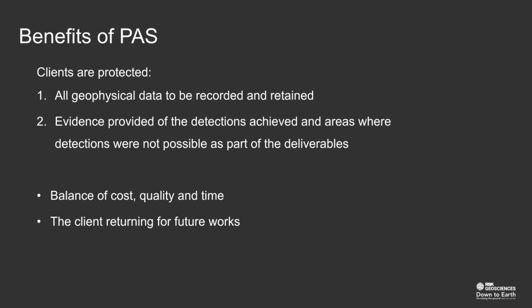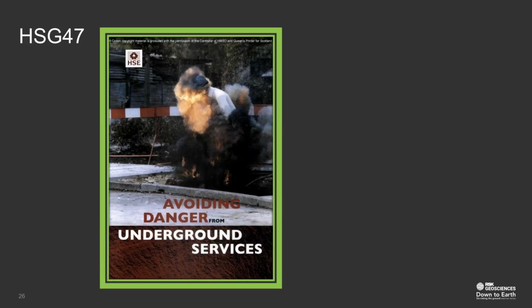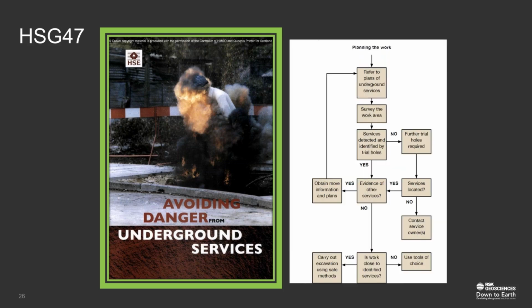Okay, so we've discussed PAS 128 in some detail from a technical perspective. So how does it tie into HSG47 and G5.15 in terms of the health and safety aspects? So starting with HSG47, this is the HSE document which provides a best practice to avoid danger from buried services when breaking ground. The safe system of work from HSG47 has to be employed. And you can actually see here that those quality levels that we've discussed earlier from PAS 128 fit into the different stages of that system.